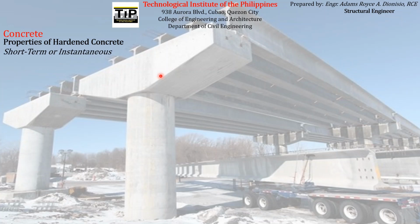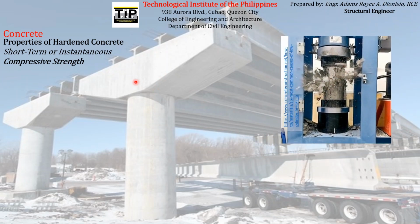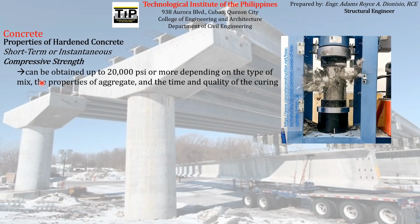So let's start with the first short-term or instantaneous property, which is the compressive strength. The compressive strength of concrete can reach up to 20,000 psi or more, depending on the type of mix, the properties of aggregate, and the time and quality of the curing. So we can actually produce different magnitudes of compressive strength depending on the type of mix, the properties of aggregate, and the time and quality of the curing, up to a compressive strength value of 20,000 psi.